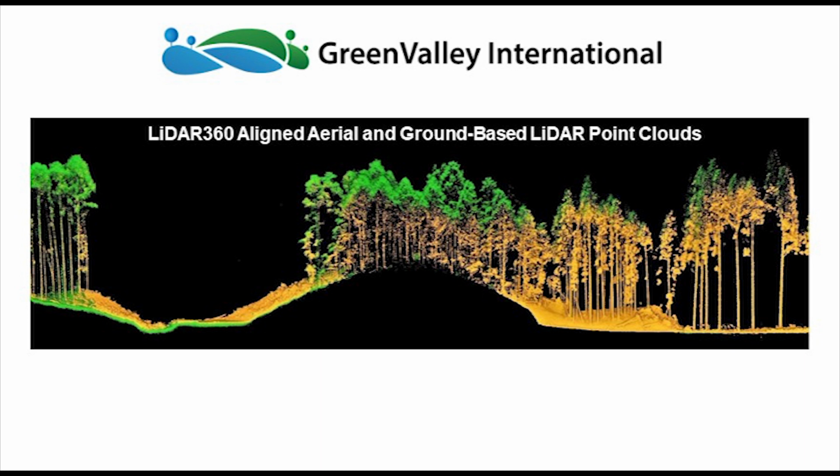The slide you're looking at is the outcome of a co-registration process that was performed in LiDAR 360's rectify tool upon the two data sets that you saw in the previous slides in order to fill the gaps in information and produce a LiDAR data set for a forest that then can be used to extract all pieces of information needed to predict volumes, generate high-resolution terrain models, or perform a variety of other functions which make LiDAR data valuable to people in natural resource management.